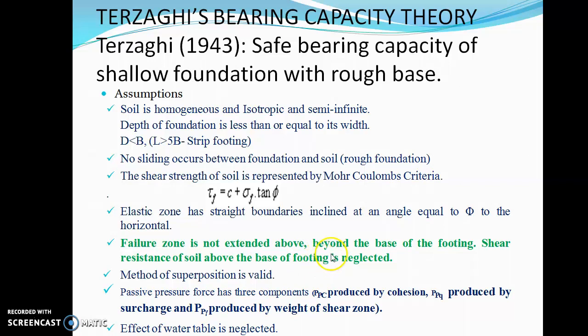Whereas in reality, when we try to create similar site conditions or analyze the soil when it fails under a shallow foundation with rough base, can we analyze it for each of these criteria separately? Like we find out the failure when only c is acting, or the failure when the soil is more of friction soil, or the failure wherein only the density of the soil is considered. All these 3 cases when we independently check, first and foremost their critical surfaces are different.